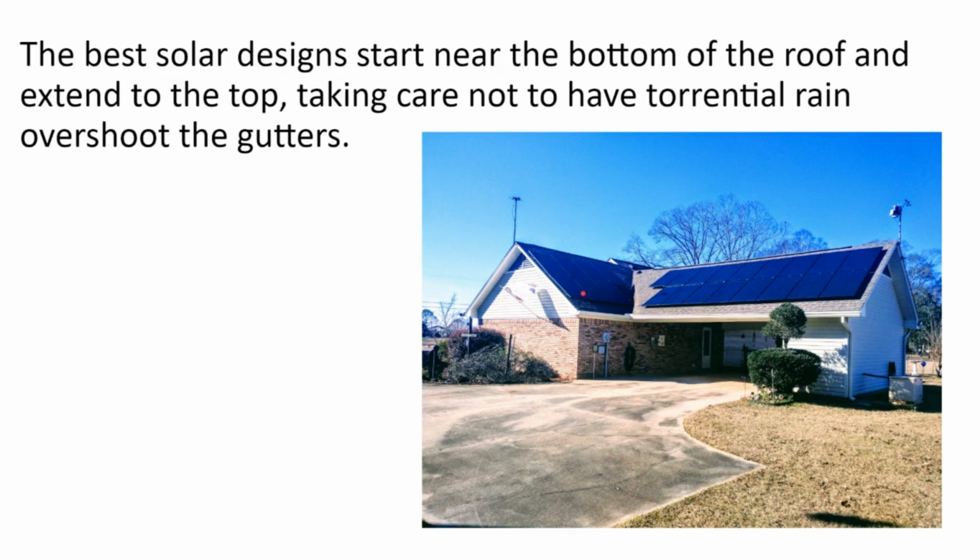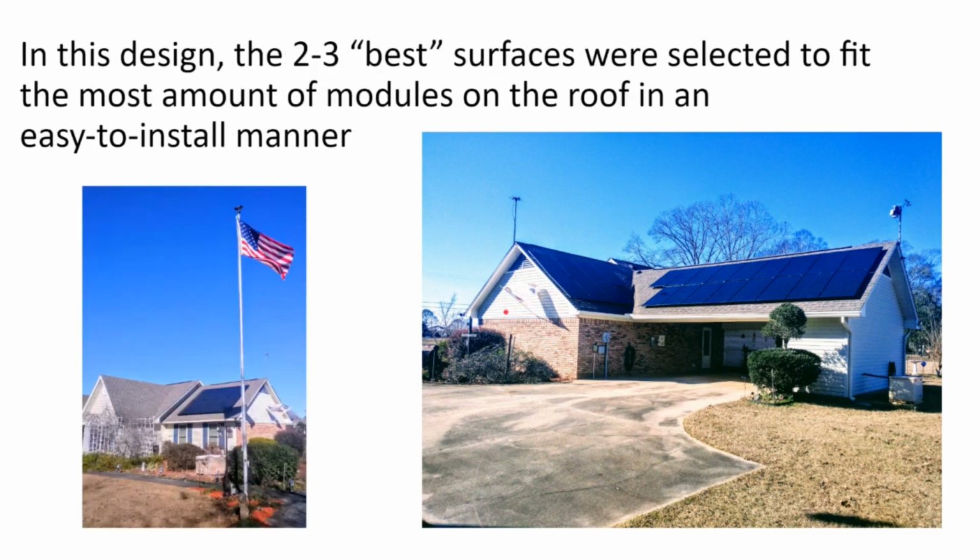If the project skips some of the design phase, such as not being reviewed by a structural engineer, nor having a third-party inspector get into the attic to verify the lag bolts hitting the rafters, nor checking with the local jurisdiction to see if there are local roof offset requirements, then it is safe to maintain a 3-foot offset from the roof ridge and roof rakes, which are the tops and sides of the roof.